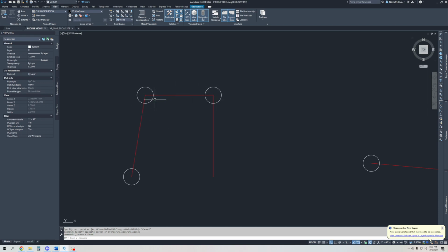And then I would have this for my front face of curb is what I'll call it, my top front face of curb. And then this would be my top back of curb. Top back of curb is going to be a very common thing that you hear. That'll be an acronym, TBC, top back curb. There's also FFC, front face of curb.